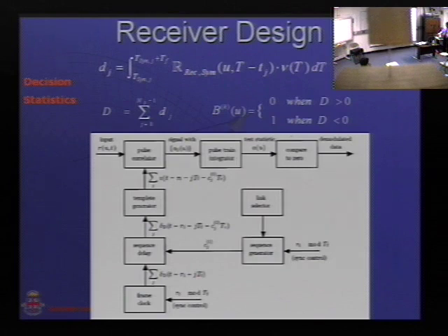So at the receive side, you generate this sequence. Okay, generate first the delta function, and you know the frame boundary, and we know what the pseudo random sequence is, because you know which user you are trying to receive, and the chip rate you already know. So the only thing you don't know is where it's sitting, at 0 or 1. You just try to guess it. Okay.